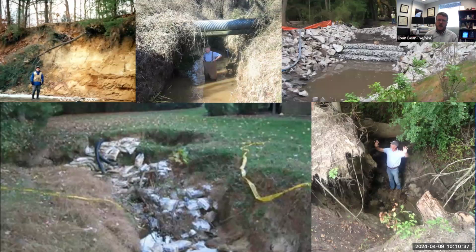Now, the increase in our flow rate, that peak runoff rate, would essentially start to erode out channels. And these are some images that I've collected over time of different examples of urban erosion. And this essentially wipes out the biology and the ecology that's in streams by eroding out the channel. Anything that's living on the channel bed basically gets scoured out every time there's a storm event.